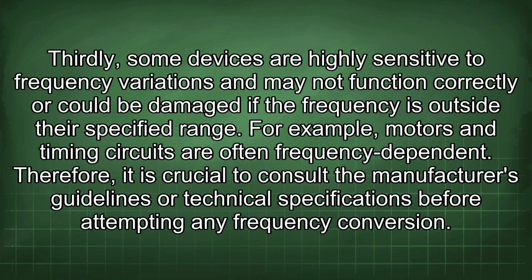Thirdly, some devices are highly sensitive to frequency variations and may not function correctly or could be damaged if the frequency is outside their specified range. For example, motors and timing circuits are often frequency dependent. Therefore, it is crucial to consult the manufacturer's guidelines or technical specifications before attempting any frequency conversion.